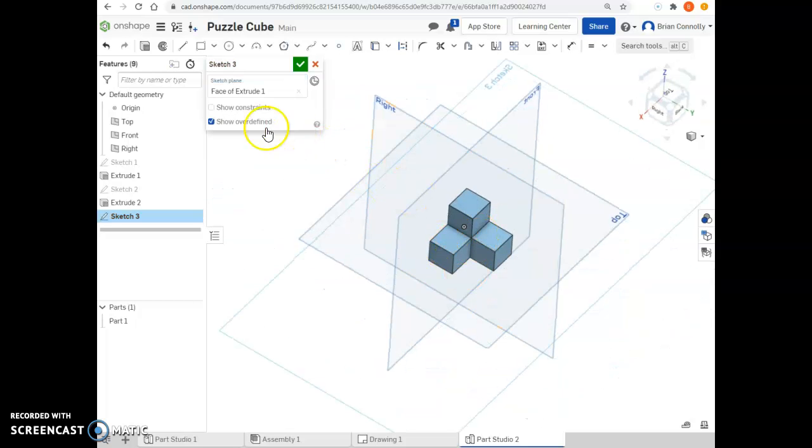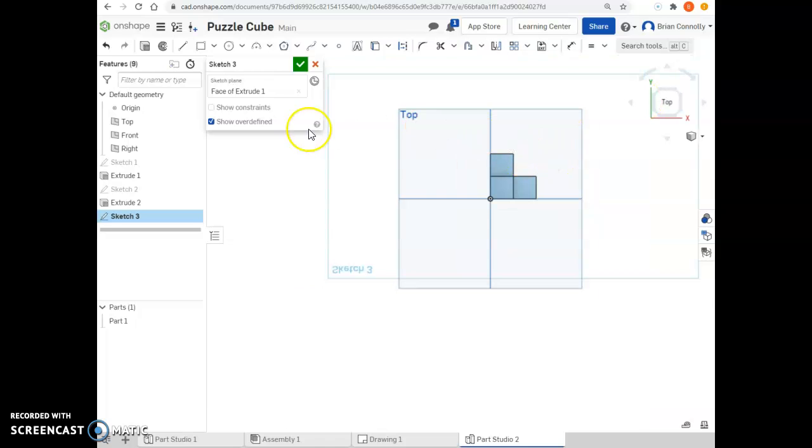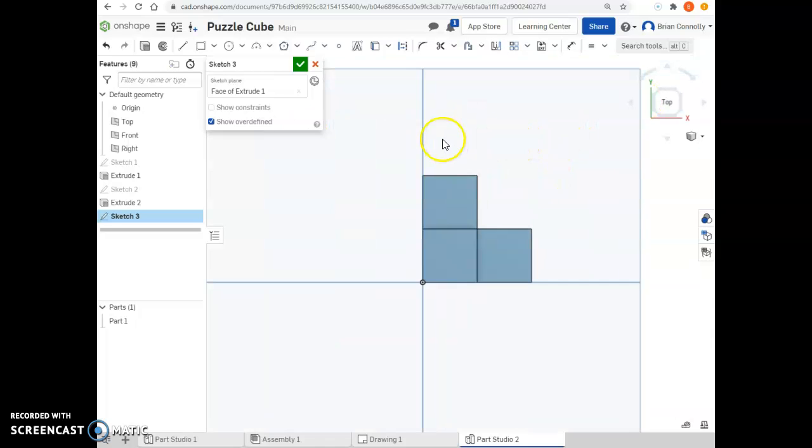That way they all relate, so if things start moving, they'll move together. And so I've got that, I've drawn that. I'm going to look at it straight on, and I can see that I have my sketch. Looks a little backwards, but that's okay. And then from here, again, I can't get the snap, although if I move my mouse there, it lines up, and if I try that for both, hey, it worked. You can see I have a horizontal and a vertical constraint going on.